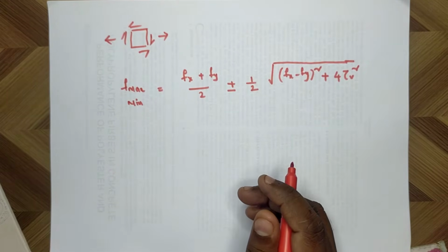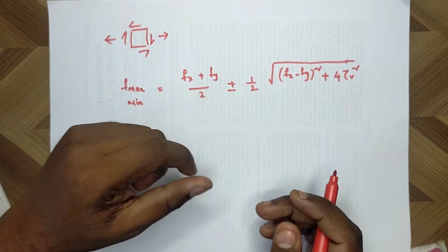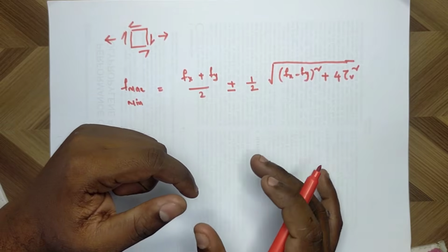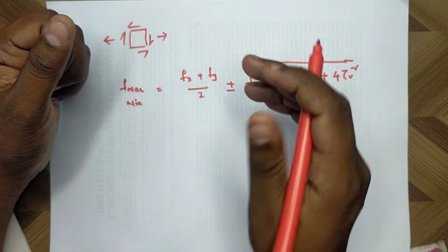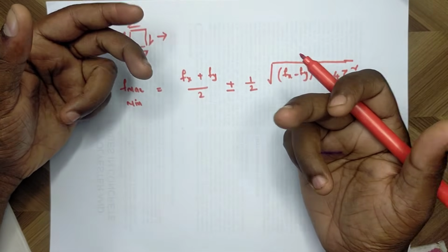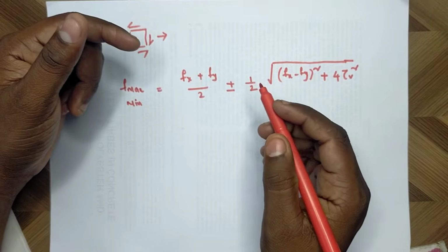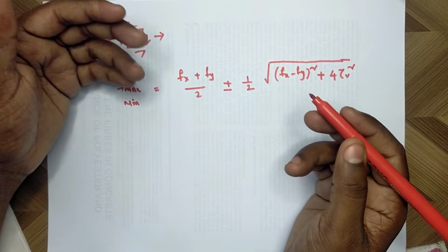Right? In general, there are 3 ways of improving shear resistance of structural concrete members by prestressing techniques. First one, horizontal or axial prestressing. Second one, prestressing by inclined cables, and third one is vertical prestressing or transverse prestressing.